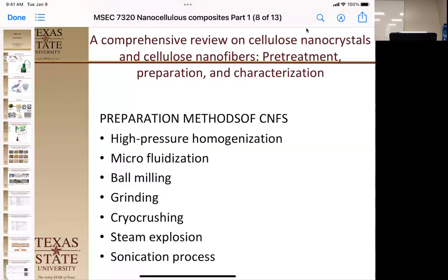Microfluidization is a little bit different. Microfluidization is where you have a pump and it goes through two holes and then they come back on each other. And so it's still a high shear point where you're going through the two small holes, but it is not scalable, as you will. High pressure homogenization is scalable. They have million-gallon ones.